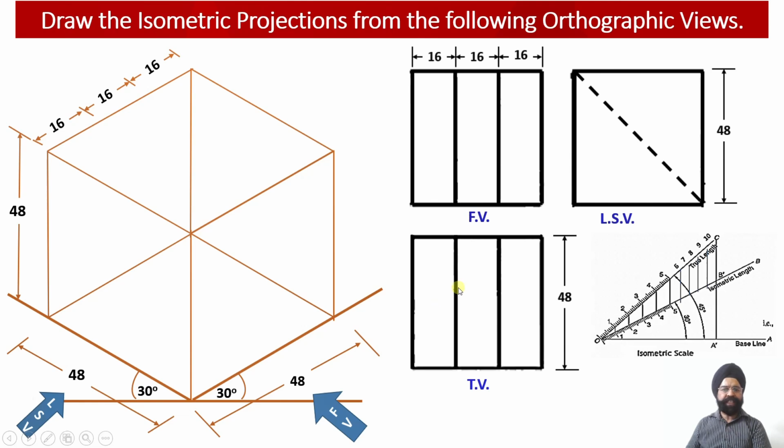So this surface and this surface of the two webs will be lying horizontally onto the top face, and this surface and this surface which is available in the front view will be located in the form of a vertical web over here, and this inclined surface will be starting from here and ending up over here. So these will be the two slant surfaces which will be available to us in the middle. So let us start with this construction.